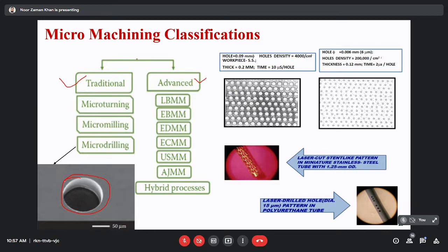Another example is milling of micro grooves and micro 3D shapes, turning of micro pins, etc. Micro milling is widely used for fabrication of micron size grooves or small cavities or 3D concave and convex shapes. And micro milling with tungsten carbide tools can be used for machining various materials such as steel, aluminum, brass for making micron size or miniaturized components.